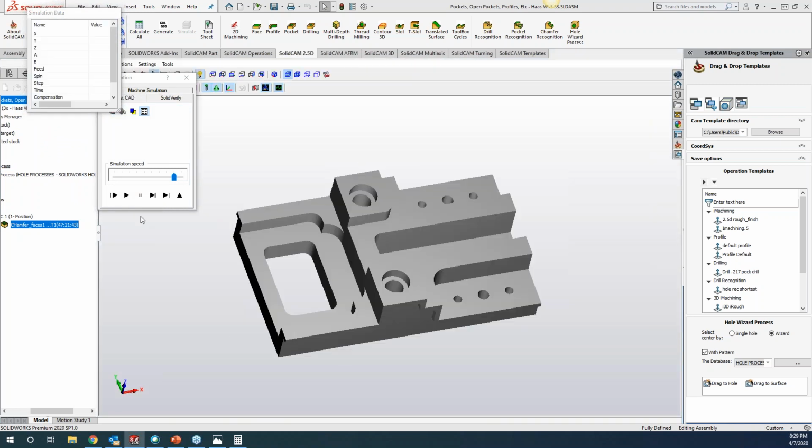Solid verify here. And that went a little too fast. We can see that we are climb cutting all these cuts in here. And like I said, by user suggestion, when you are running very brittle materials, that doesn't work out so well because you will actually chip out there.